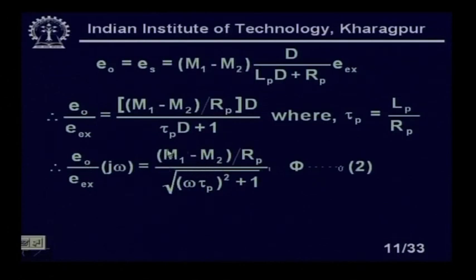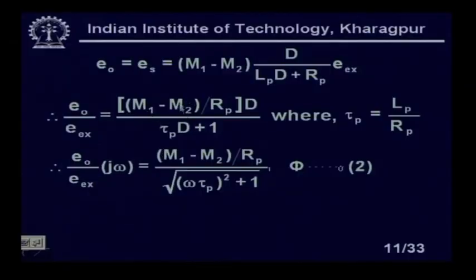All other things remain constant, M1 will vary and M2 also will vary. If I move the core up, what will happen? The M1 will increase, M2 will decrease. If I make the core go down, M2 will increase and M1 will decrease, is it not? So, x is hidden within M1 and M2. Obviously, this output voltage will be proportional to the position of the core, or x.